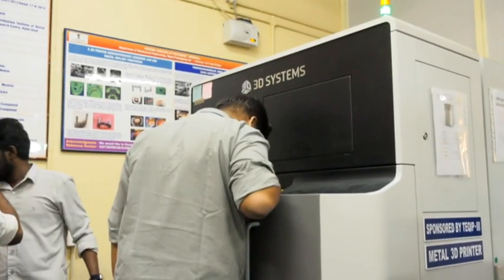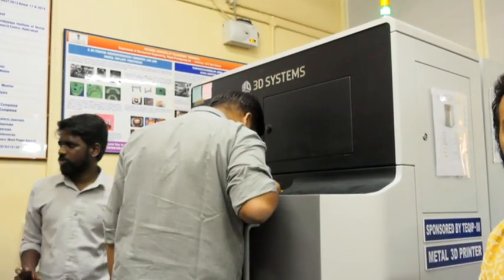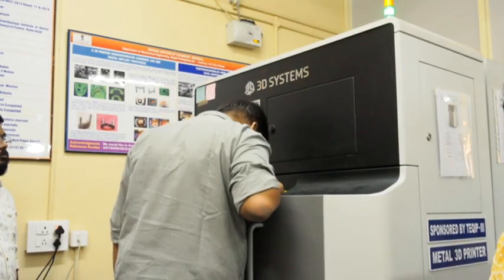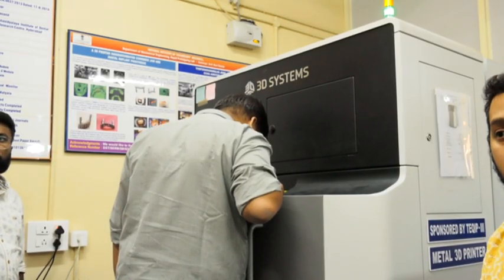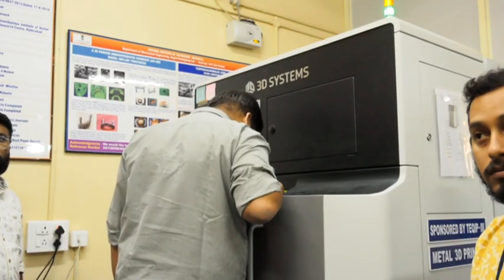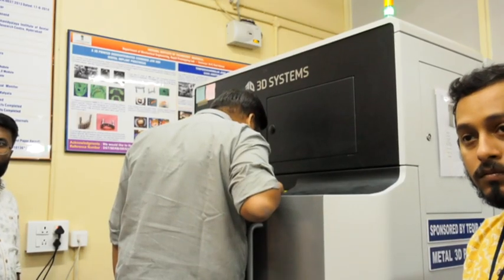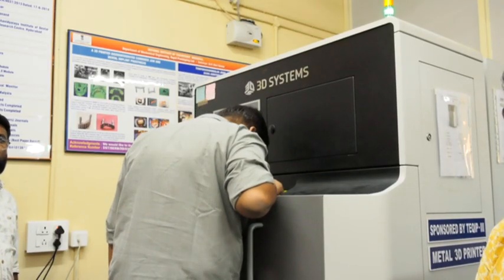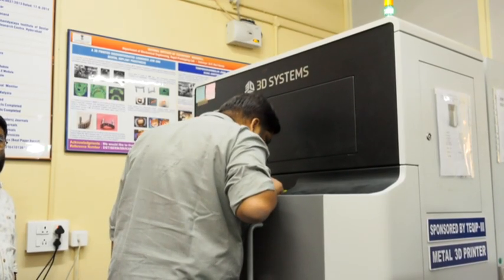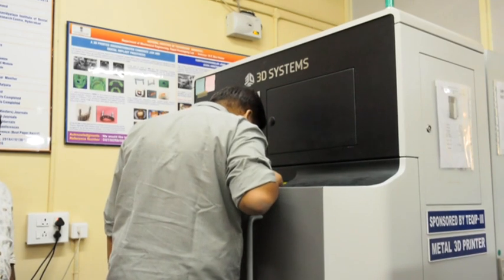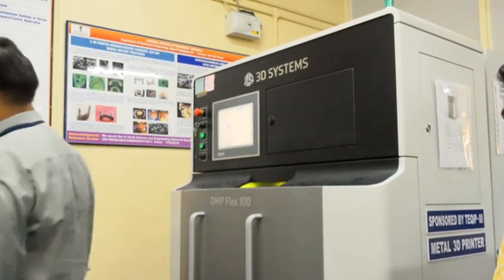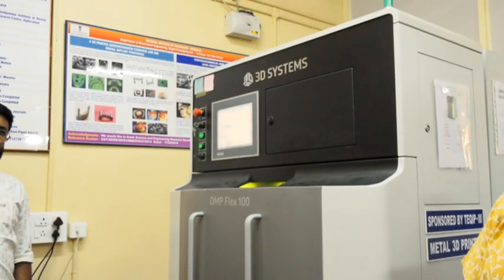While evaluating the surface hardness or roughness, do we test it after sandblasting or before sandblasting? We do the roughness before sandblasting only, so it can be done as built. If you are not satisfied, then you go with after sandblasting. Normally we'll get a very good finish, maybe around 10 to 15 Ra value.